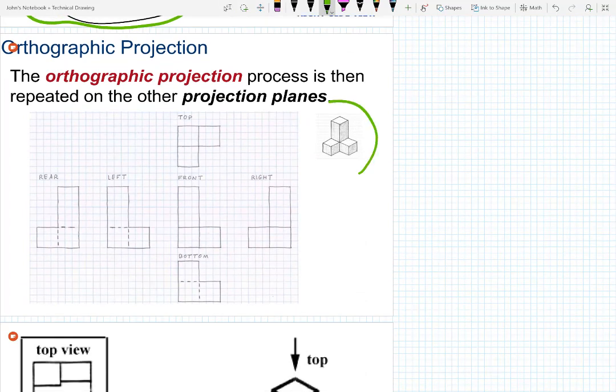Okay, here's an example of a structure that we may have made before, and if you just think about it for a minute, you can see that the front view usually is always going to come from this direction. So you can see the front view there. The right view, convince yourself that it would look like this, with these lines here corresponding to, actually, that one and that one. And then the top view, hopefully you can convince yourself that if you're looking straight down here, this is what you'll see. I'm going to just leave these off for a little while.